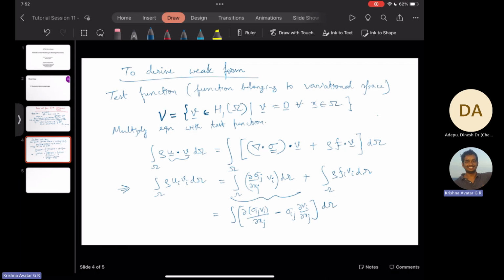Then you can see the first term here looks like divergence of something. So you can write it as, say, sigma v divergence. So v_i can be written in front. Then from Gauss theorem, you will see that it becomes a surface normal integral, right? Exactly. Then it becomes something like sigma_ij dot n, you should take, no? Yes, and then sigma_ij n_j v_i d omega.